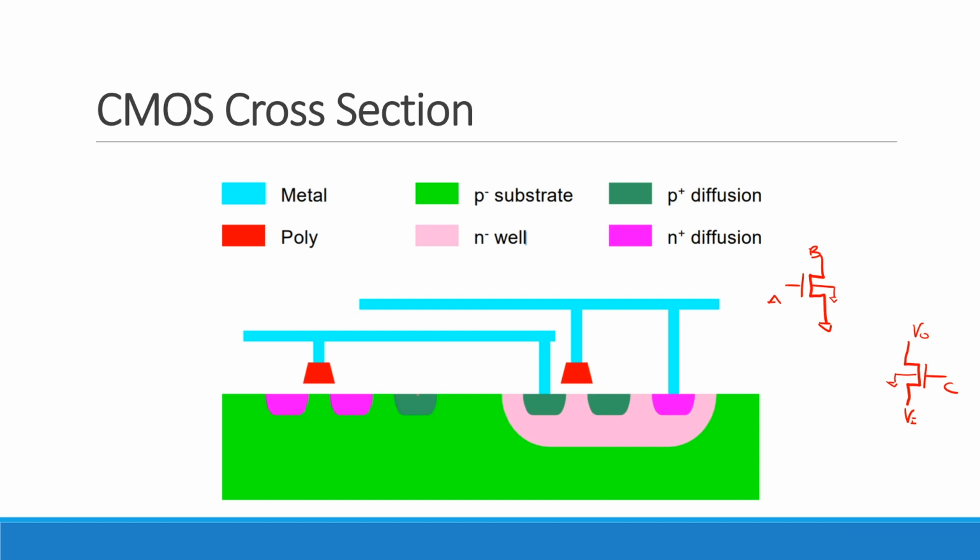There's a bunch of junk in between there, right? There are some parasitic bipolar junction transistors. In fact, even simpler than that, you'd like to say that when you tie that thing to ground, it's really ground. But of course it's not, right? There's some resistance there. There are also some diodes over here that have some capacitance associated with them. Let's say there's another transistor, and there's some resistance over there. So in fact, all those transistors are somehow coupled to each other through this big substrate network, okay?